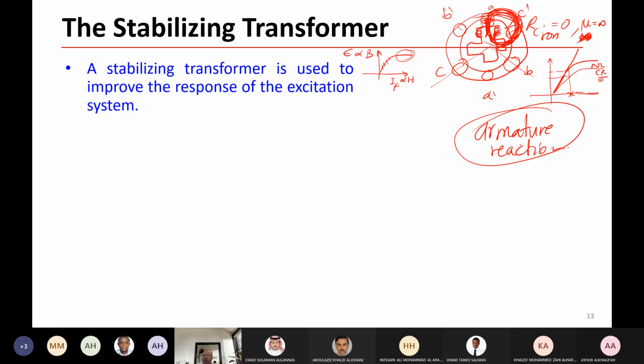The other component of the armature reaction is distorting the field, or the flux in the circuit, which would be perpendicular to the flux, and this one will be opposite to the flux, which is the demagnetizing component. So the flux decreases due to the armature reaction, and the voltage will be lower. Okay, is it clear, Abdulaziz?